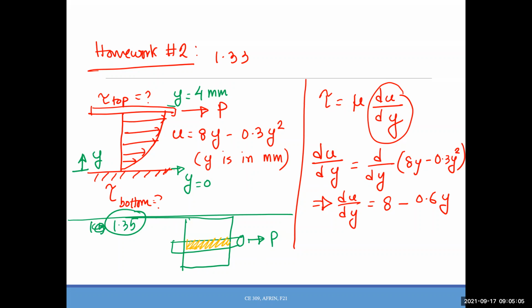And for question number 1, any one of you have any answer for question number 1? Did you calculate the density or specific gravity, specific weight for the lab experiment? Okay, do that and make sure you use the correct unit, in SI and BG. For SI system, the density should be above 800 at least. If you get 1, 2, 0.5, 0.3, that will not work. It should be above 800 kg per meter cube.